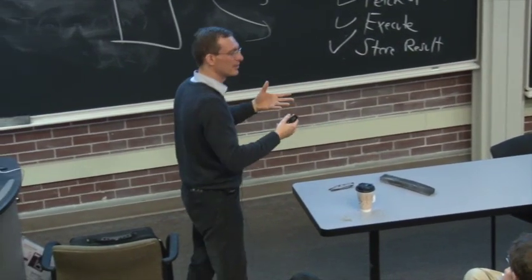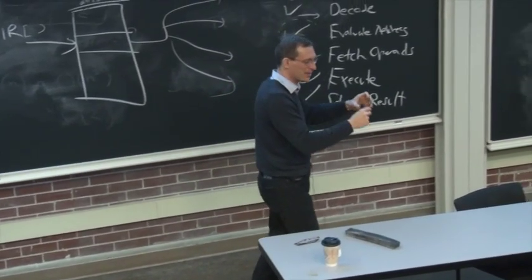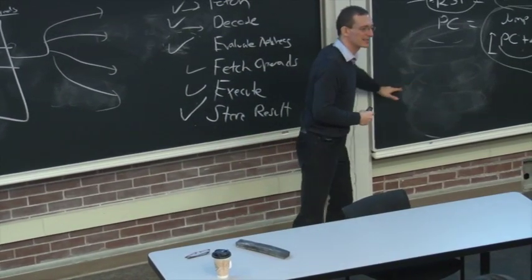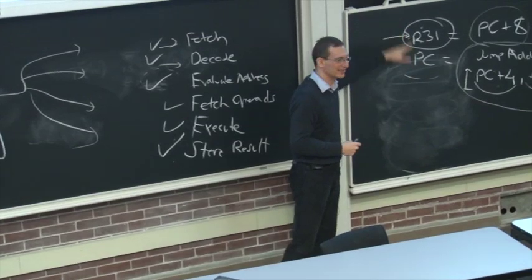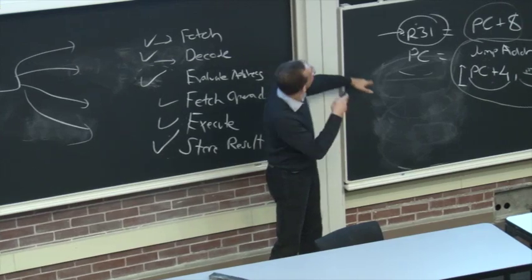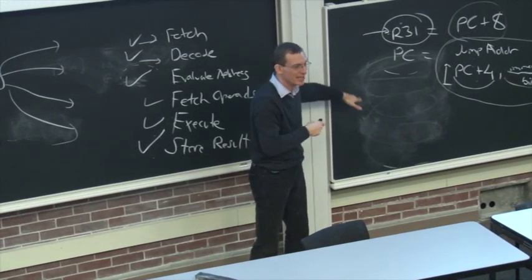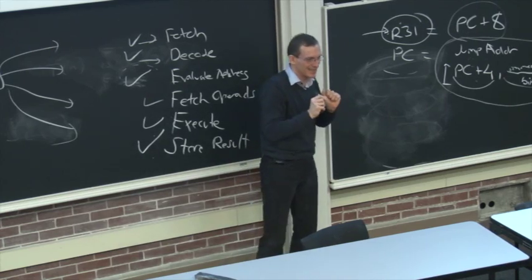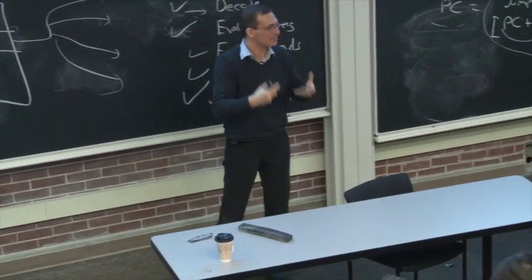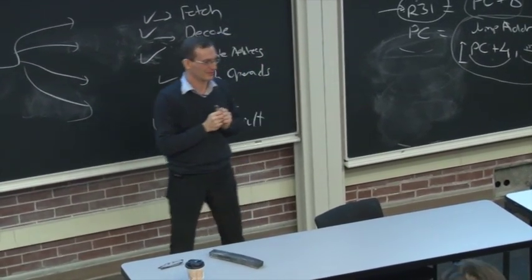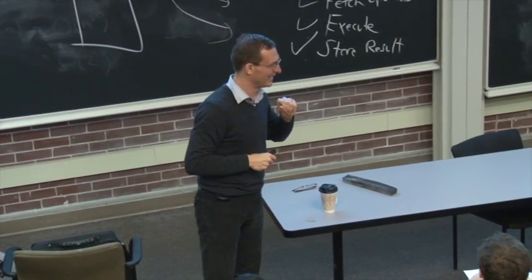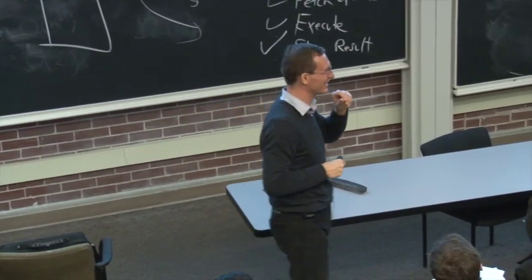This is in the spirit of reduced instruction set computers. Now, the instruction may become more complex. You may need to encode more things, but the instruction is much closer to your hardware. Remember that semantic gap picture that I drew several times? If your instruction specifies most of your control signals, then most of what you do in the microarchitecture is data path processing. Now, you cannot do it perfectly, because there are some control signals, for example here, that need to be determined based on the execution. But yes, that's a very good point. And you're probably thinking like John Cocke now, when he thought of it in the 1970s.